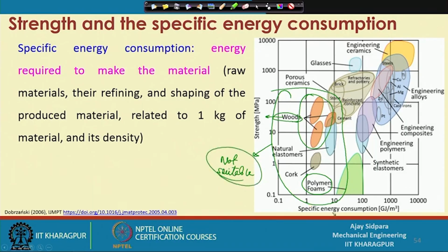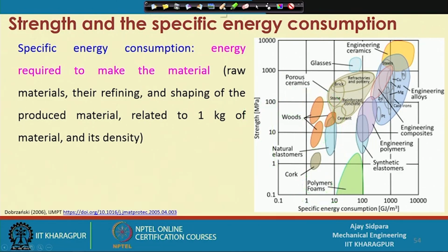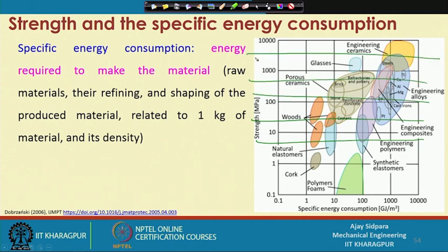Now, what you have to think about is that you need high strength. If you go in this direction, now see, let us divide this part in terms of strength, correct. So, these are the strength axes. Now if you look at this particular thing, suppose you are going with 1000 MPa or 1 GPa. At that time you have a reasonably good amount of material, but the problem is that for processing those components you have to spend a huge amount of energy. That is the big problem.